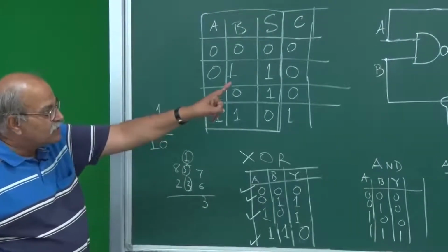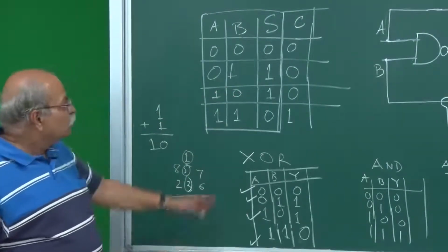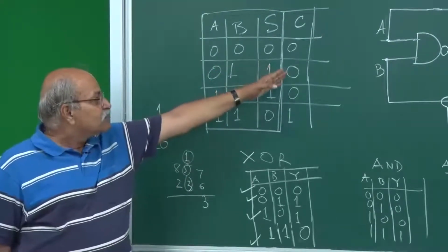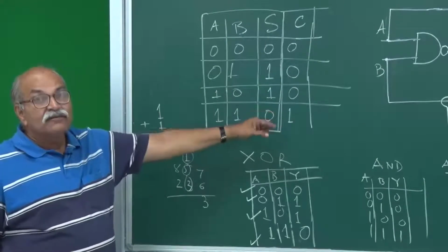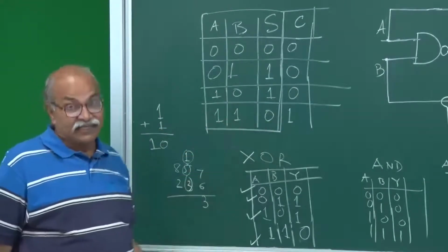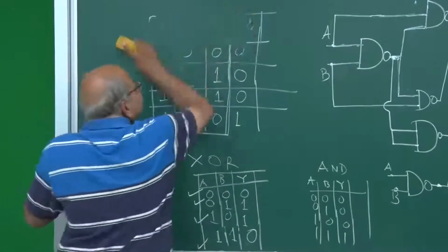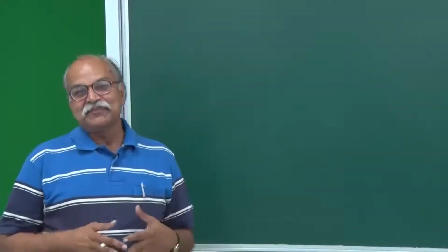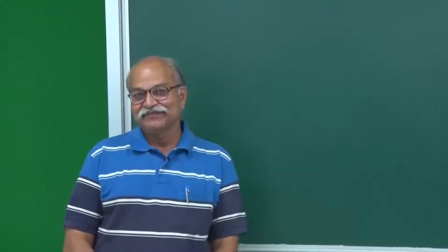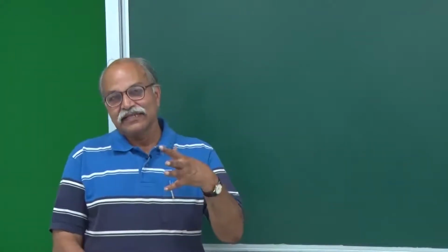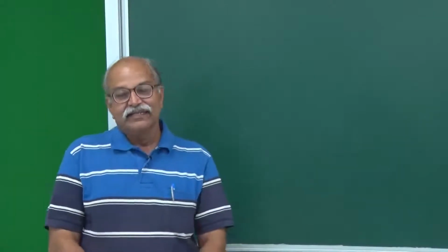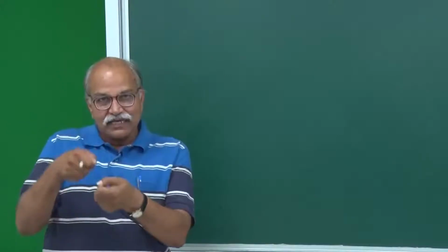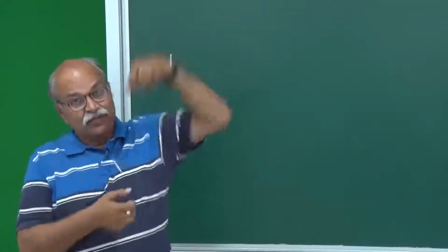So, this is known as half adder circuit, and if I do a sum of 3 digits and then find what is the sum, what is the carry, then it is called full adder circuit. So, I will give you a broad idea of how this full adder circuit can be designed, and there will be 3 inputs that you understand. 2 numbers are to be added and then the carry, all 3 are to be added.